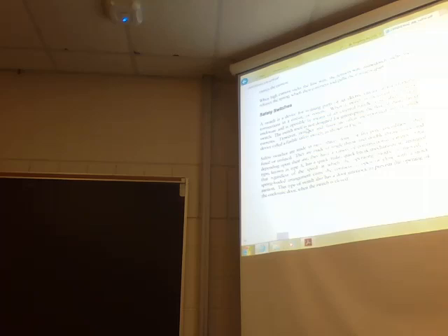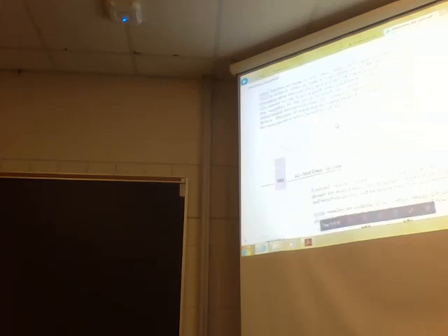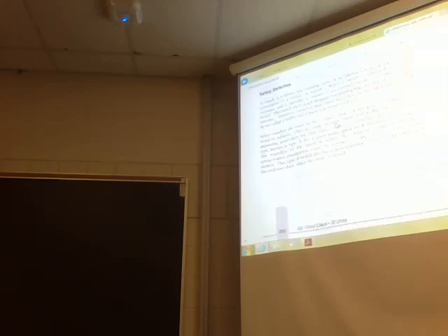This type of switch also has a door interlock to prevent the opening of the enclosure door when the switch is closed. The reason for the quick operation, quick make, quick break, is to reduce the amount of arcing. If you take a disconnect and move the handle slowly, then you're actually causing welding in that switch. So if it's spring-loaded, it bangs open and bangs closed, with the least amount of arcing possible if it's used under load.